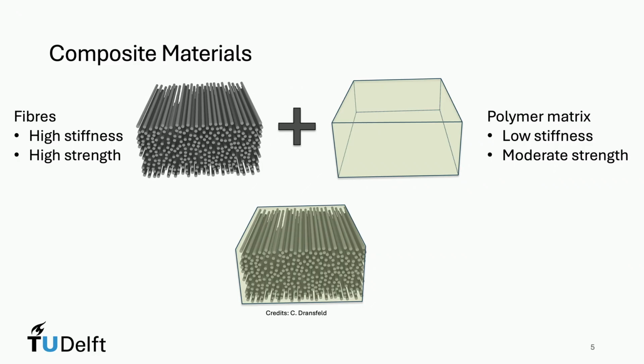Mainly glass fibers are used in the blades. And with the push for longer blades, we added carbon fibers to the main structural element to increase stiffness. These composite materials also present some challenges in terms of circularity. While it is durable and long-lasting, the two materials need to be well adhered to each other during use for optimal performance. Therefore, they're difficult to recycle, as we can't separate the fibers and the resin from each other without a lot of energy input.